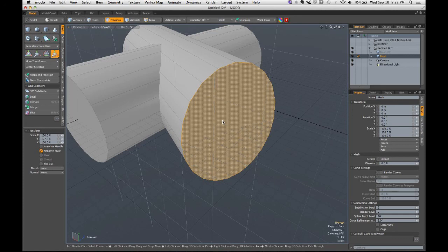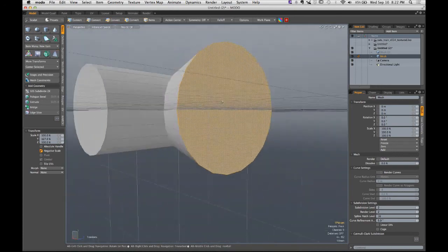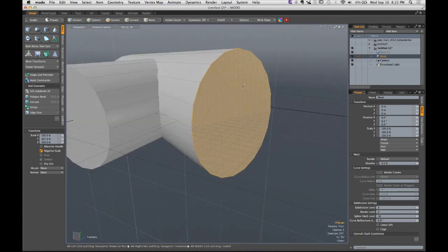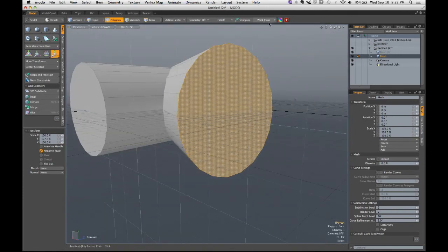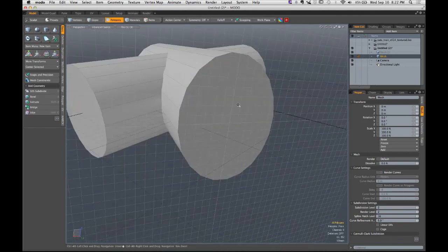Other questions? How did we put that working axis onto something again? You're not going to need to do that for this, but just out of curiosity, you can make sure you have something selected, the element that you want your work plane to be moved towards. I shouldn't even have shown you guys this. So that polygon's off axis. I've got it selected. If I go to Work Plane, Align Work Plane to Selection, okay, now I can center things.